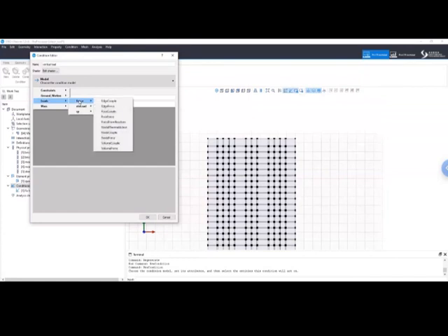Now, as you know, in OpenSees, you have distributed load only under the command for beams, but unfortunately this command is only available for beams. Now in this case we are not using beams, we are using continuum elements. So what we have in OpenSees actually is just plain nodal loads. But fortunately in STKO we created some automations. As you can see here you have edge force or face force.